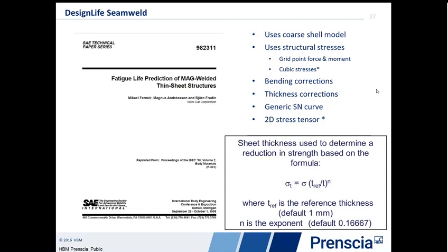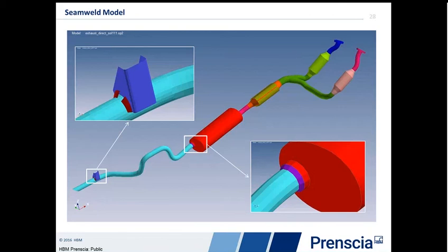What we've done is we've implemented this in the frequency domain. So we've taken the vibration load provider and tied that to our model. So we're back looking at our exhaust system, and I have two areas where I've welded. I have a bracket welded to the exhaust tube, and these welds here are what we call fillet welds. They're welding plates that are basically perpendicular to one another. I also have a second weld farther up on the exhaust system where the exhaust tube goes into the muffler.